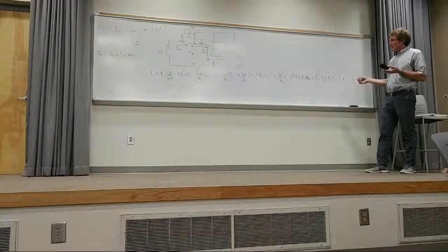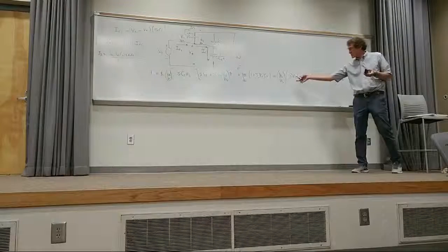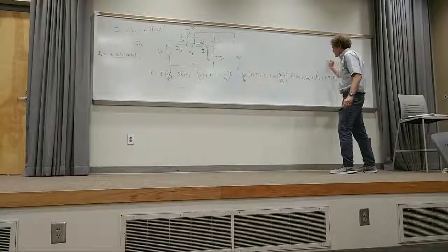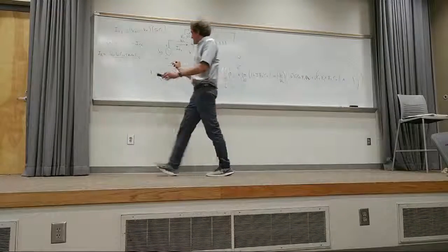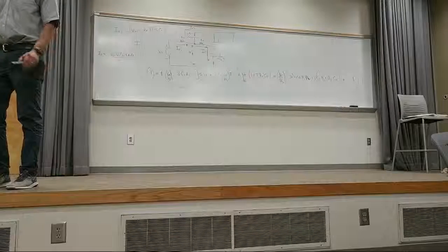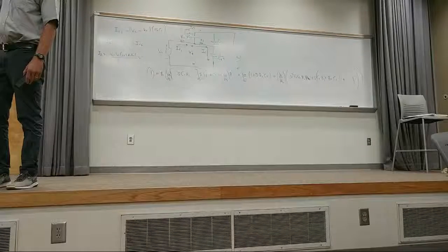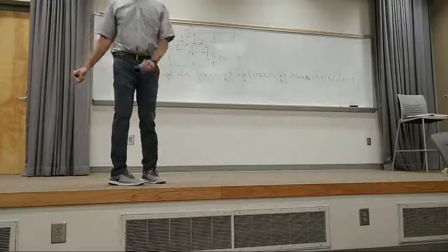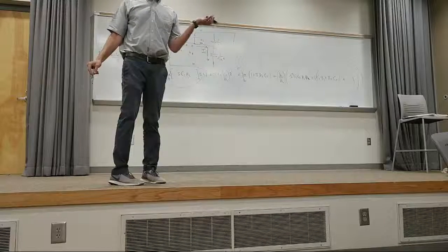What we really do in a second, we would divide everything by C1, C2, R1, R2, so the coefficient of this would be 1. But you can see the only thing I have to do is take this right here, this entire chunk, and divide it into 1 now. Don't I, class? And then, in fact, I would get the transfer function. How many see that? That's what the book has as an answer. They may give you values for R1, R2, C1, C2, and ask you for the actual impulse, the h of t or something like that. But you see, this is the way it's done.